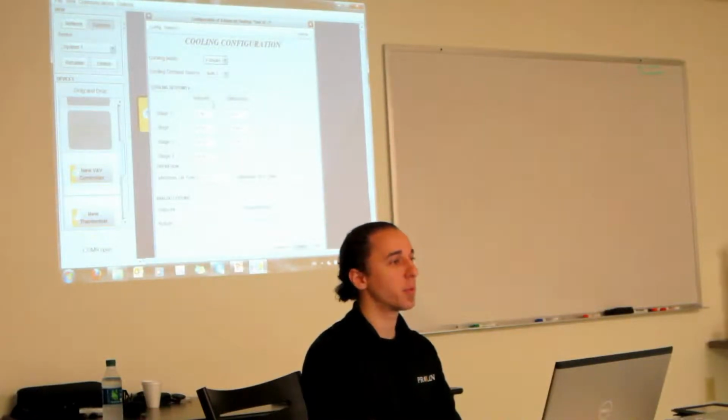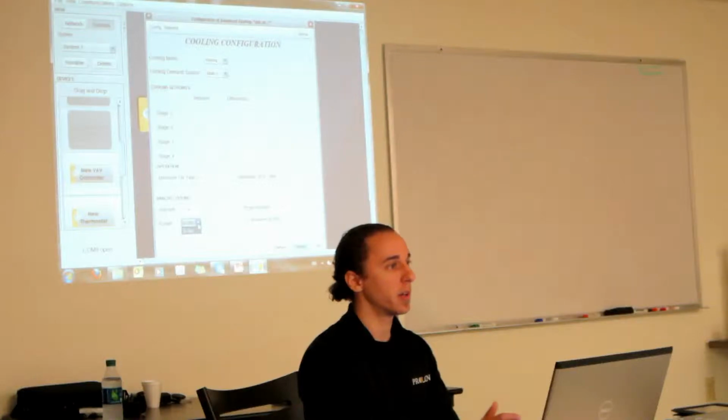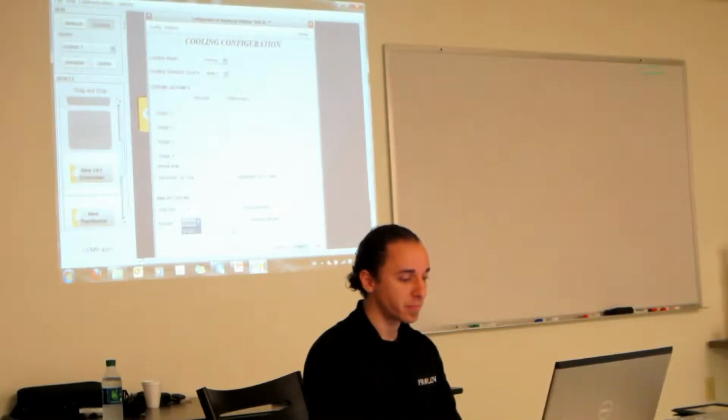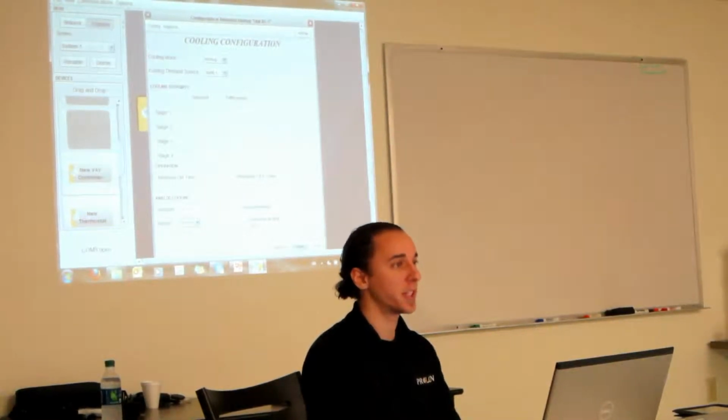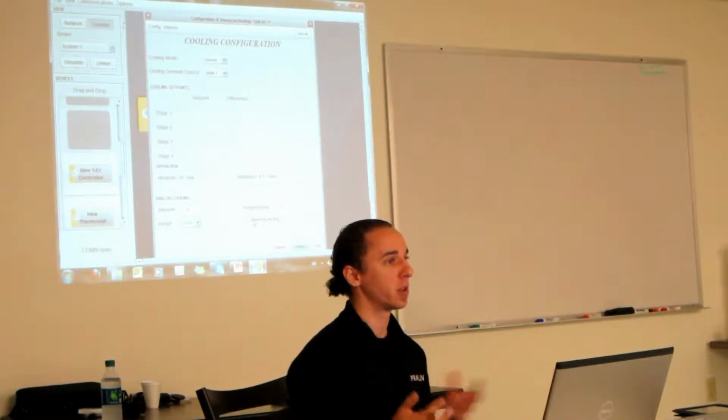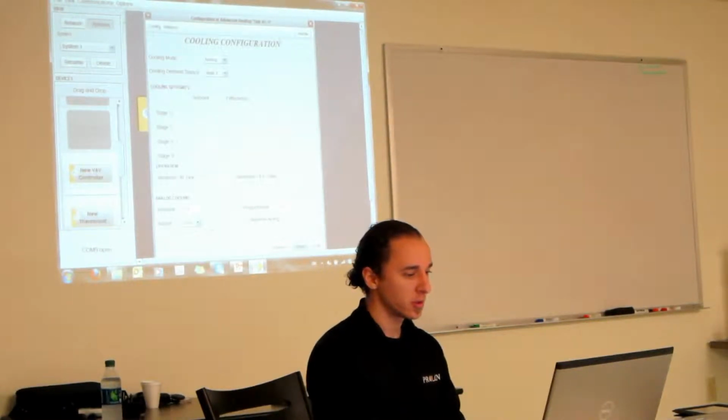So here you have all your set points and your differentials. Our minimum on time, minimum off time as well. If we go into the analog, all this becomes grayed out. We have our little analog right here. So what's our range? 0 to 10, 2 to 10, depending if it's like a valve or something like that. It can be reverse acting, so if it's normally open, normally closed, as you wish.